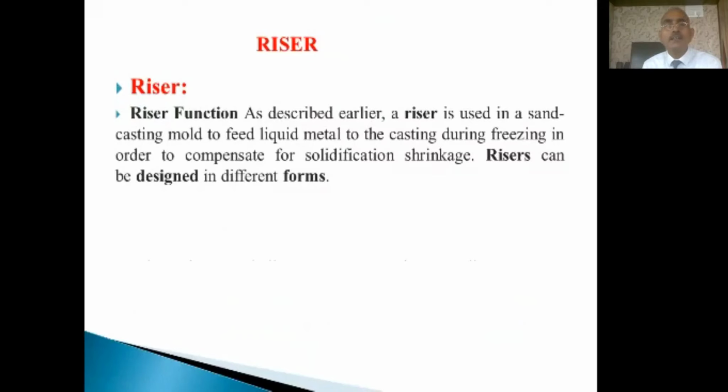So as described, riser is used in the sand casting to feed the molten metal in the casting during freezing. Whenever the metal freezes, it compensates for shrinkage during the solidification process.